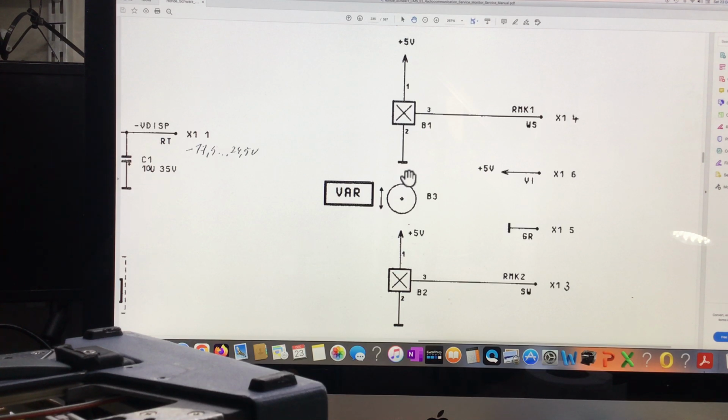So if, for example, there is foreign debris off this rotary magnet, some filings broken off that's stuck to one of these sensors, then it would essentially trick the digital circuitry into thinking that the control's been turned permanently one way or the other. And that's why when we physically rotate the control on certain levels, for example RF level, frequency, etc., if you remember, it just incremented continuously even after we'd stopped turning this control.